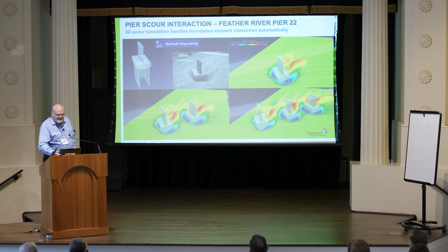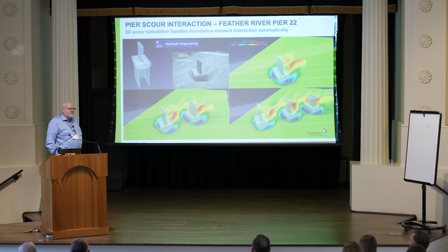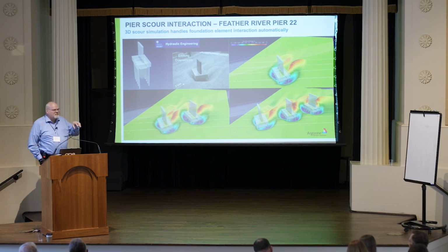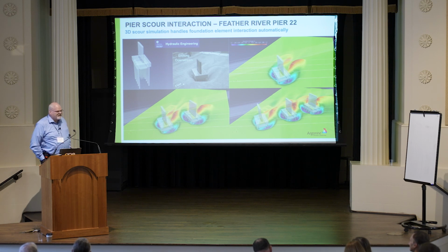let me go back to this one here, right? So the one on the top left, you just load it in your CAD software, and you load it in 3 different locations. You save it as a single STL file, you go, right? So the easiest thing with debris would be to just make it part of the bridge structure file, right? At some point, I even put some riprap in there, right? The riprap cannot move. I mean, that's one of the problems, right? So when you put things in as a bridge structure, it's static throughout the whole thing. But you see interesting effects when you clog up these openings with debris, that's for sure.